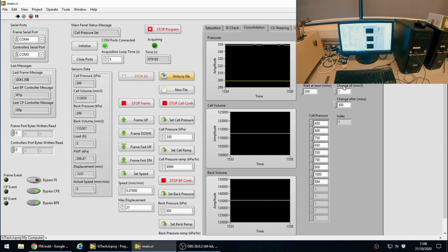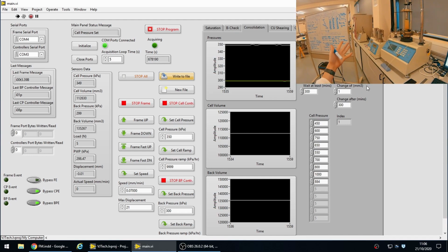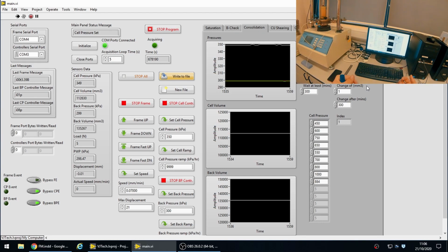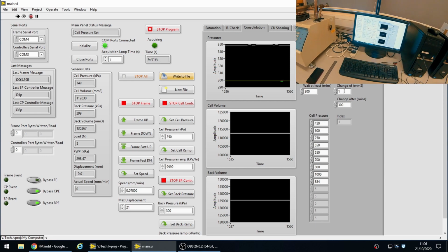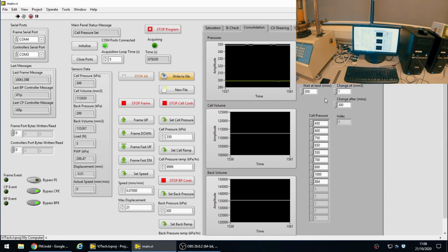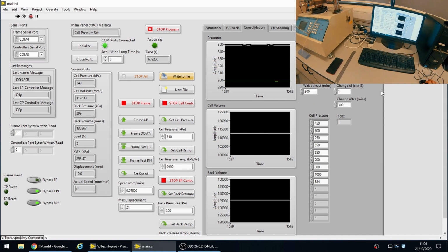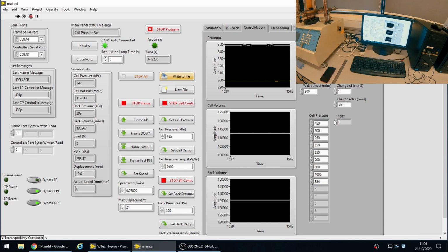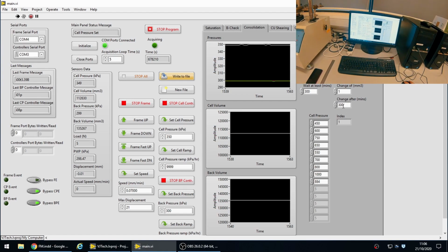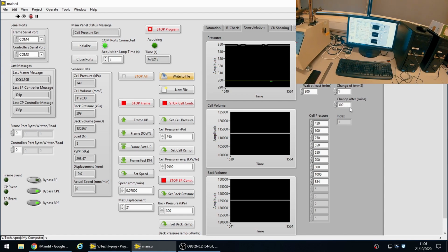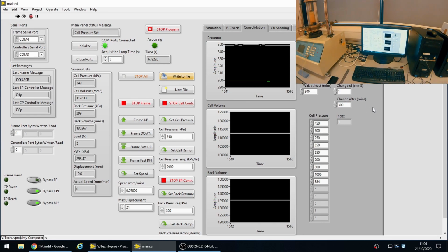So, looking back to our controller software again, in the fields here where we have wait at least minutes for a change of millimeters cubed, that's what we're talking about when we are thinking in the standards of wait for 300 minutes or 5 hours for a change of 1 millimeter cubed. If within 5 hours 1 millimeter cube change doesn't happen, the next stage of consolidation will occur. Failing that, we've also got this box here that says change after 300 minutes. So there's two options for our software there. We've given it two options.